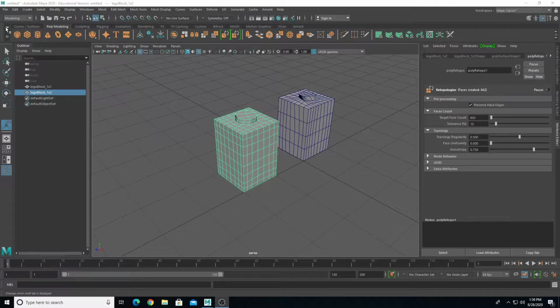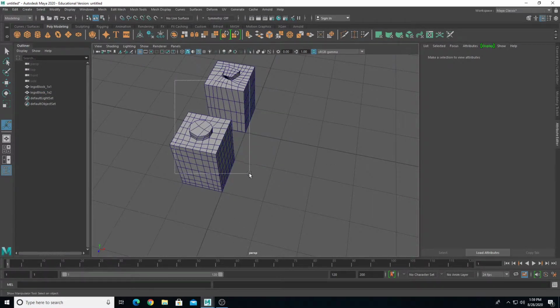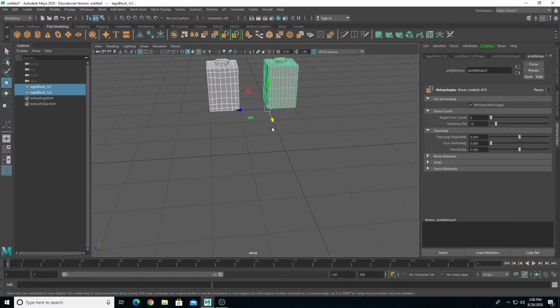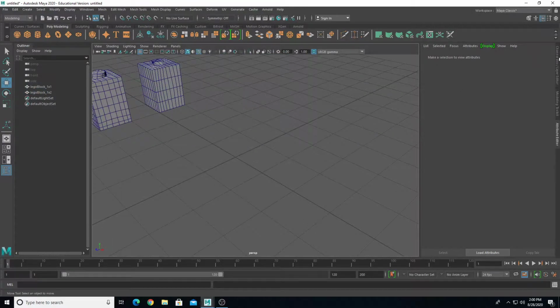The second method, we're going to use a base cube and start with only quads and just adjust and edit those quads through the use of extrude and move, rotate, and scale. So it's just a different way to create models. Let me move these out of the way from the previous video. You can go back to the previous video to look at more examples from the subtractive method.